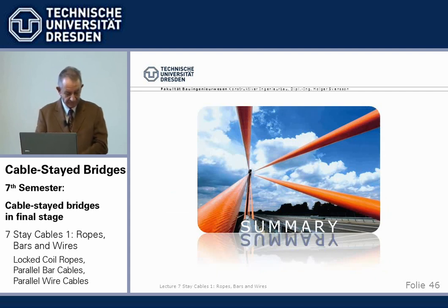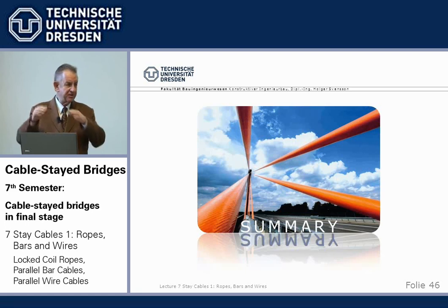Basically, to sum this first part of stay cables up, the stay cables are the main load-bearing member of cable stay bridges. Their stiffness governs the deflection of the beam and so on. The beam stiffness is much less than the stay cables. So they are extremely important for the load-bearing capacity of a cable stay bridge.